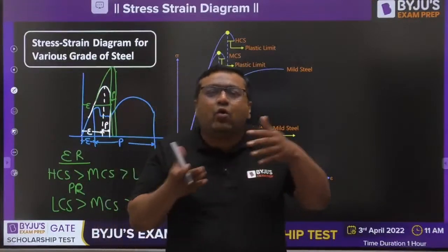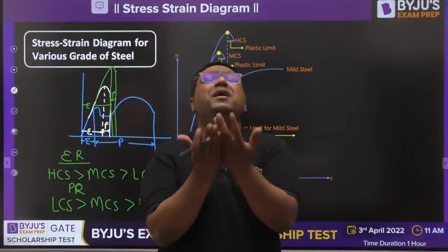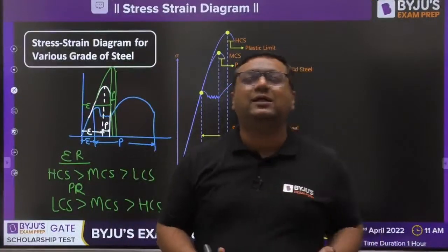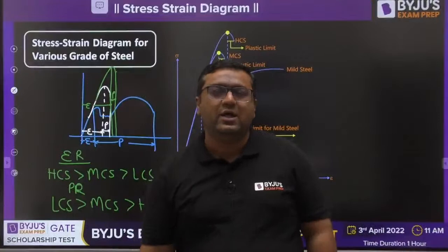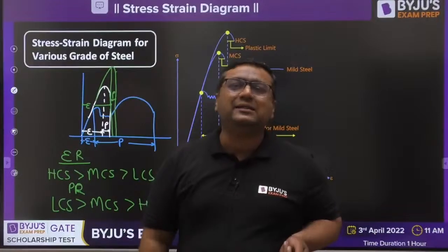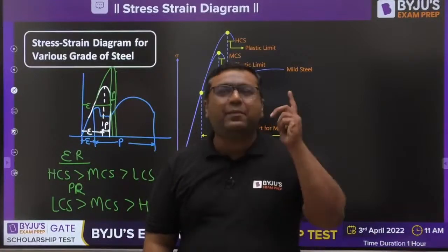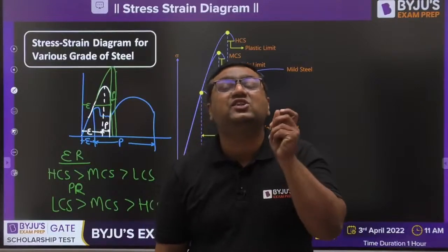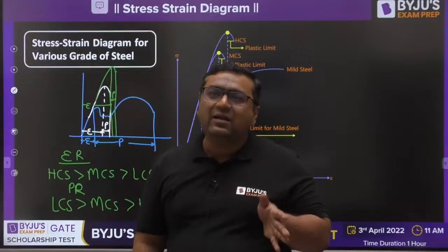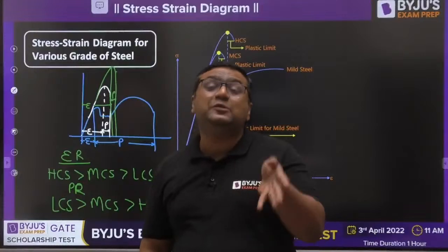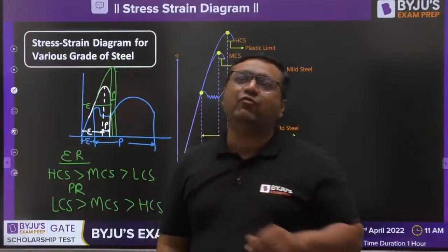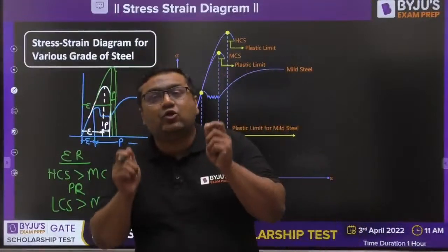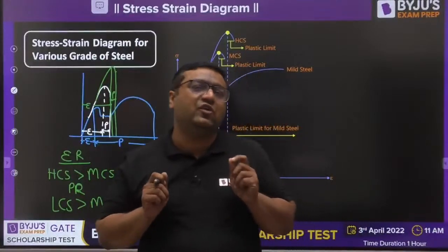We make a rod into a wire only if it is going to remain a wire. So for ductility, we want plastic deformation. That is why ductility is defined as the property by virtue of which a material can withstand tensile stresses and post elastic strain, meaning plastic strain, is more than 5%. Then only a material is said to be ductile. This is the real definition of ductility.